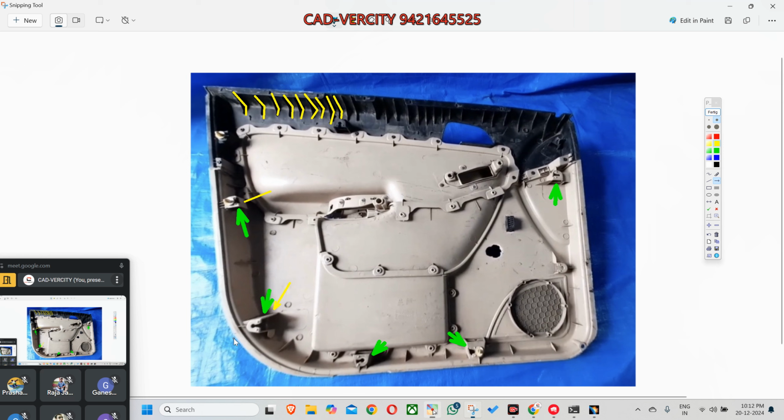Agree, everyone? Yes, sir. Now tell me, we will need this extra material for the assembly of the pin. Now tell me, what is this, lifter or slider? Lifter. Why? Because here you can see the undercut is in the inside direction. Why inside? Because there is one wall in front of the doghouse.